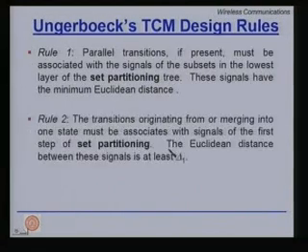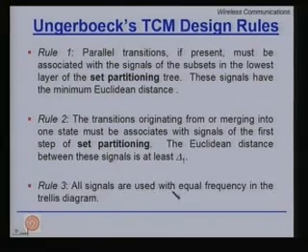So, what are the design rules? Rule 1: parallel transitions, if present, must be associated with signals of the subsets in the lowest layer of the set partitioning tree. We just saw how to do set partitioning, because these signals have the maximum minimum free Euclidean distance. Rule 2: transitions originating from or merging into one state must be associated with signals of the first step of set partitioning. Rule 3: all signals are used with equal frequency in the trellis diagram.